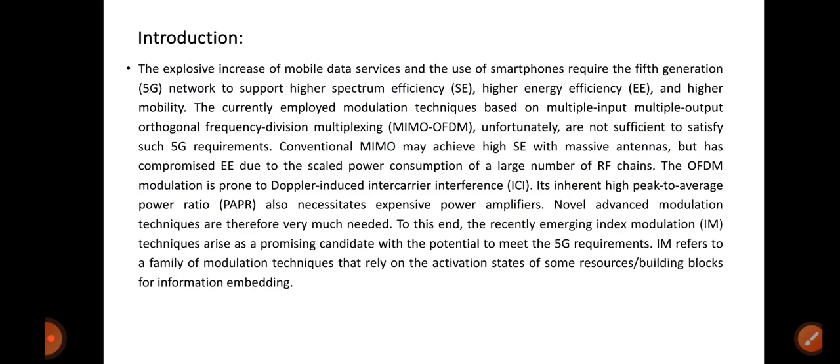Conventional multiple-input multiple-output may achieve high spectrum efficiency with massive antennas but has compromised energy efficiency due to the scaled power consumption of the large number of RF chains. The OFDM modulation is prone to Doppler-induced inter-carrier interference.